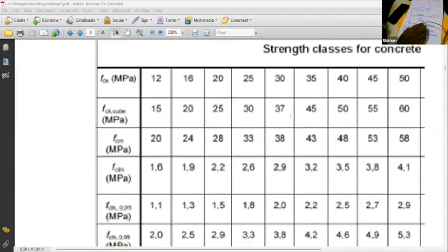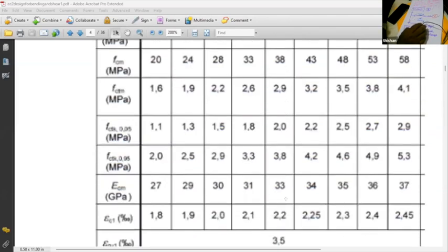35, 40, 37, let's say 37, 33. So elastic modulus would be around 33, whereas the other concrete, the type B concrete, might one day achieve 35 and it might even become 36. By the time you are selling your apartments, the building has become much stronger than you ever thought originally. And what is the time you need the very good dynamic behavior with respect to wind-induced accelerations? At the beginning of the project, by the time you sell your apartments,